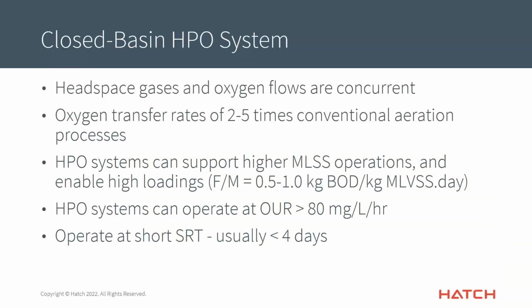So generally the way they work is the headspaces are in series, and they flow in the same direction as the liquid. Oxygen transfer rates of up to 2 to 5 times your conventional aeration processes can be achieved, partly because that headspace contains a comparable volume of oxygen. If you had just air, that would be close to 5 times as much oxygen in that same amount of gas. That leads to very high oxygen saturation concentrations in your liquid, which is good.